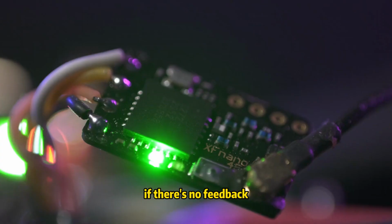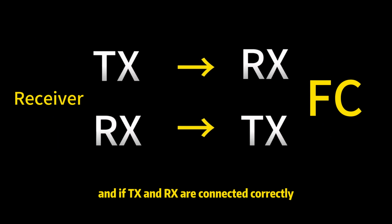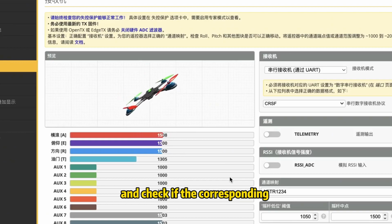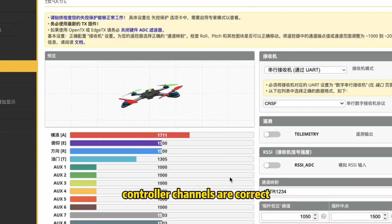If there is no feedback, check if your receiver is powered on and if TX and RX are connected correctly. If it still doesn't work, try a different port. Come to the Receiver tab and check if the corresponding control channels are correct.